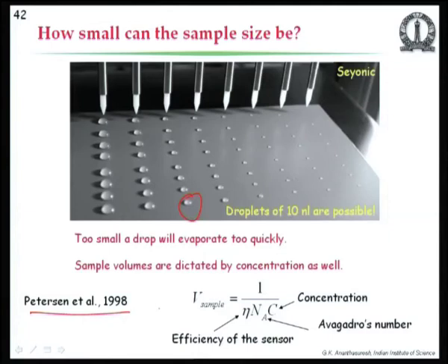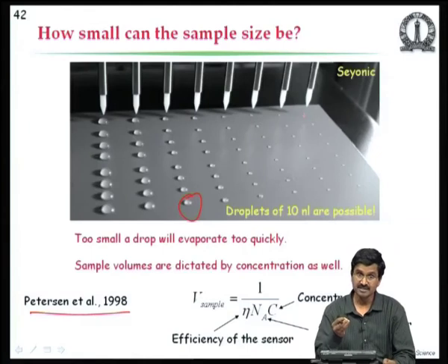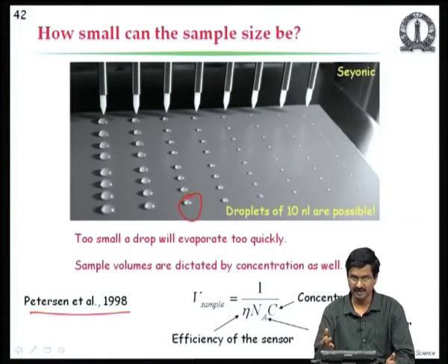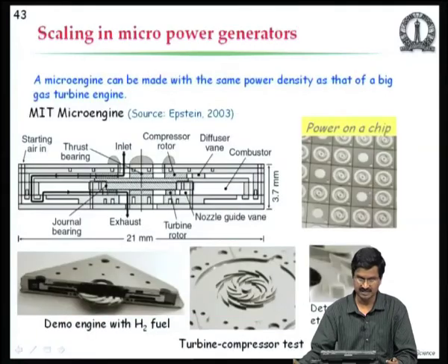And here there is a small capillary putting all these drops. The last row is quite difficult even to photograph, the paper says, because even before you take a photograph, this drop will evaporate. If you take a small volume, the surface area is more than it is at the macro scale, so it will just lose its water content and dry up. So, that also needs to be kept in mind. A lot of scaling effects need to be kept in mind when analyzing these micro systems.